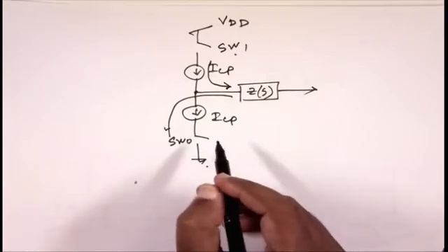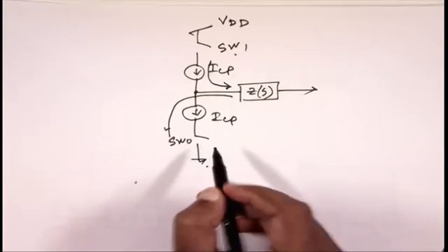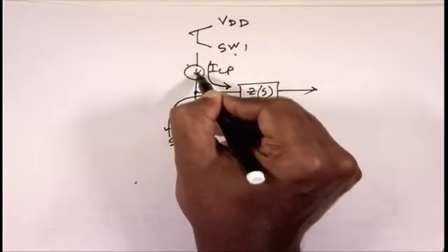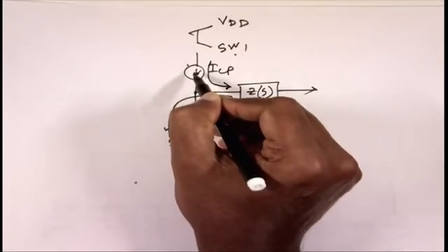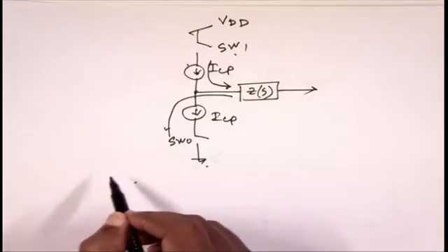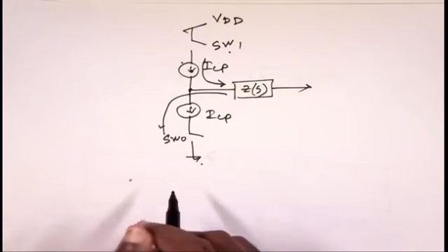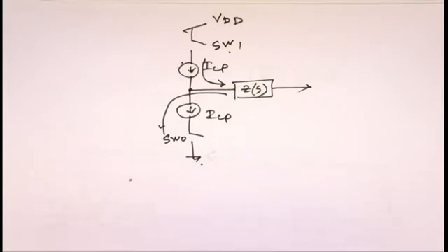But the charge pump design is actually not straightforward, because when you are switching, making it on and off, if this is a current source, it means that the transistor would be in the saturation region. When you make it off and then try to make it on, it's difficult for a current source to suddenly go into the current source domain. That means the transistor will not go very fast to saturation. So I have to go for the current steering logic and all these things.